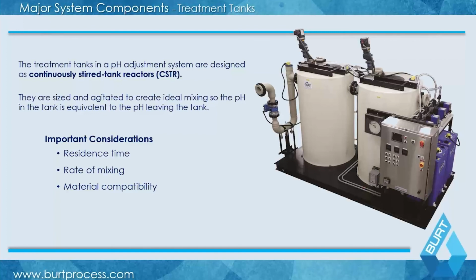Obviously, we're dealing with acids, bases, and other aqueous chemicals here, so material compatibility is also important. And by and large, most pH neutralization systems are polypropylene or some kind of thermoplastic material. Occasionally, you'll see fiberglass for high temperature and sometimes stainless steel, but 95% of pH neutralization systems are going to be polypropylene by nature.